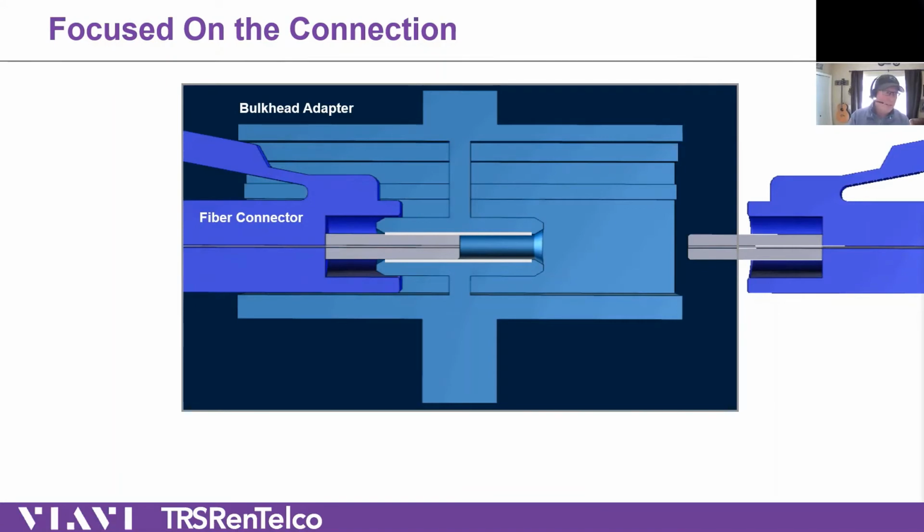So what's left in a fiber network that we have to deal with from an installation, maintenance, and ultimately a tested measurement issue that we have? Where do we come in? The connectors, period. At the end of the day, 80% of your problems that you can remedy are your connectors. And I do mean splices in that too as well, by the way, but we're going to focus on the easy stuff because splices are, hey, I got something bad, I got to roll up a fusion splicer and put it back together, and then you just test it. But connectors are the number one point of failure. Again, roughly 80%. So how does a connector work?